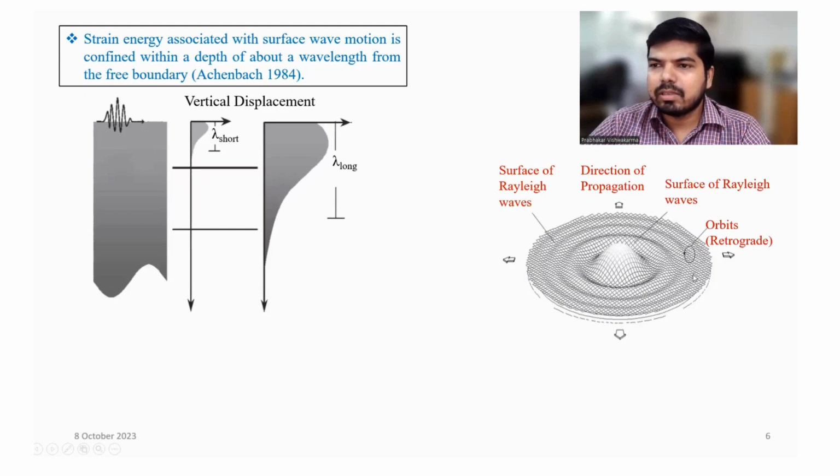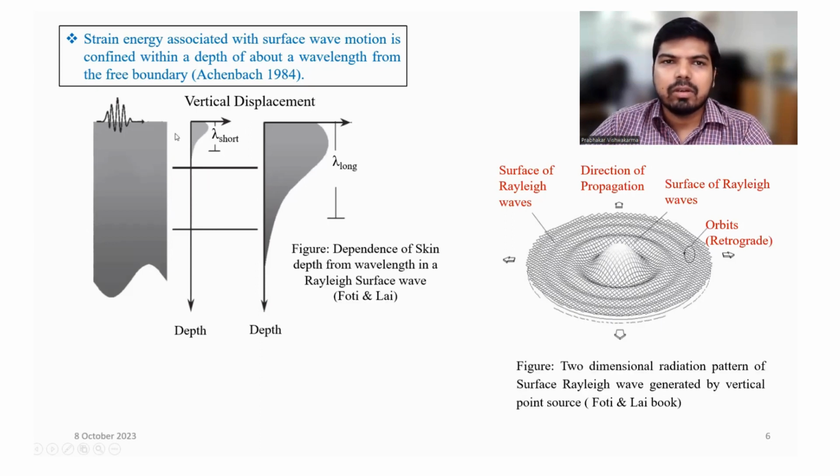So in these pictures, you have applied the load here and the wave is propagating. But how is the energy going to be dissipated along the depth? That is known as how the strain energy is going to dissipate along the depth. If you have a smaller wavelength, that will have shallow penetration. If you have a longer wavelength, that will have a deeper penetration depth.